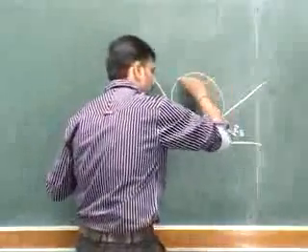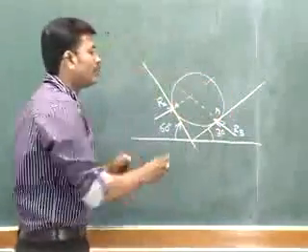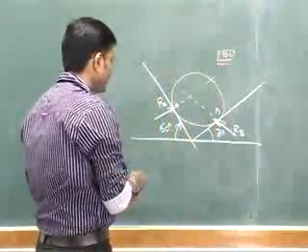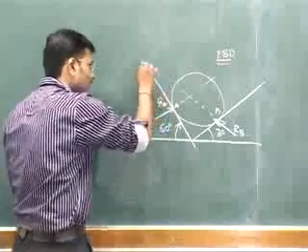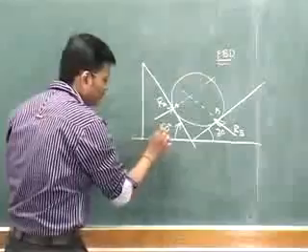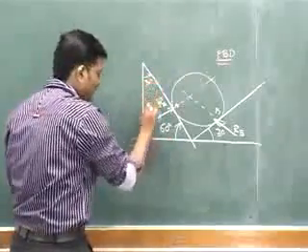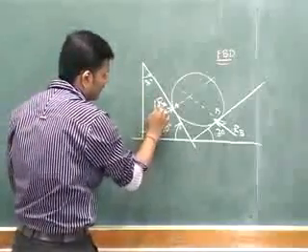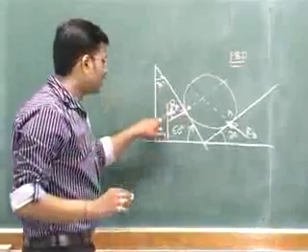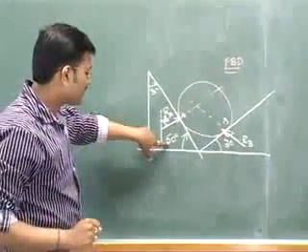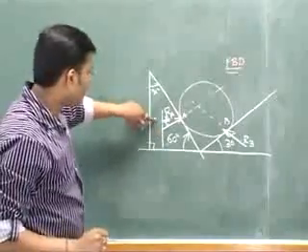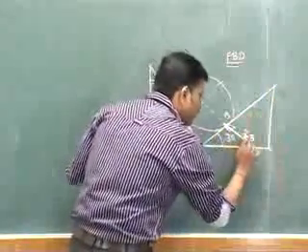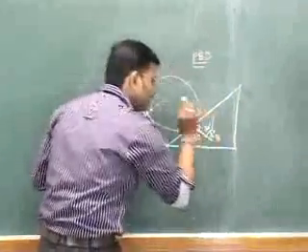So I have to first draw the FBD, that is the free body diagram, for this ball. But before that, we have to calculate the angles of these forces. If this is 60, this will be 30, and this will be 90. The angle with respect to vertical is 60 degrees. Whatever is the angle with respect to horizontal, that will be the angle with respect to vertical when it is acting in normal direction. The same condition applies, and the vertical angle comes out to be again 30 degrees.